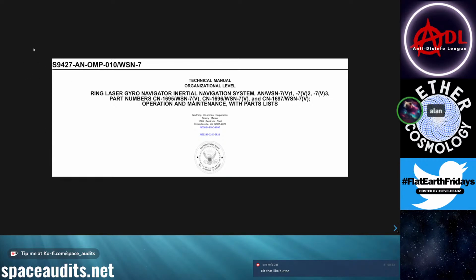This is a basic description of the ring laser gyro. Using light to measure rotation is based on the principle that the speed of light is constant. The time required for the light beam to traverse a given distance is independent of the motion of the medium in which the light is traveling. For this reason, if the light were to travel around any circular path, the time required to complete one revolution, 360 angular degrees, would be independent of whether the path is stationary or rotating.